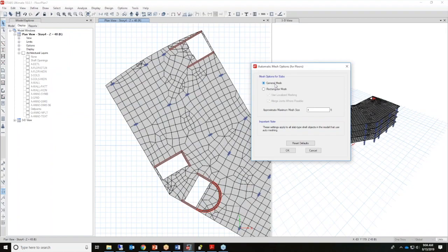Okay, so what are some other options? The rectangular mesh is the next one. This option is typically recommended for more rectangular, more regular slabs. This option restricts the quadrilateral elements, as you see here in the general, to be used in rectangular and is acceptable for rectangular slabs. This option will create a substantially larger number of elements in the analysis model, which can significantly affect computational time.